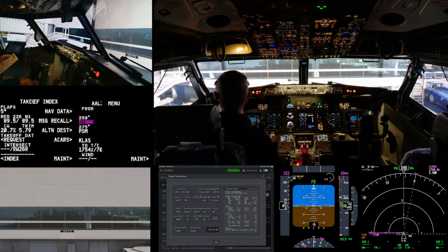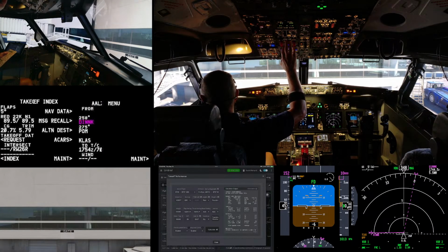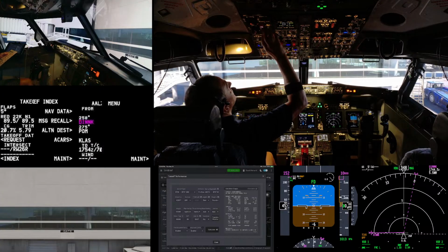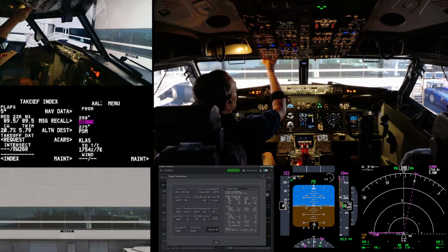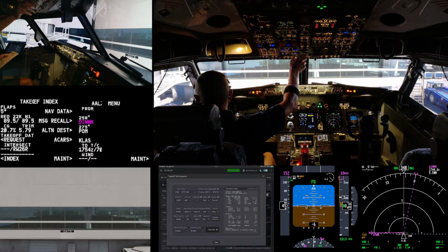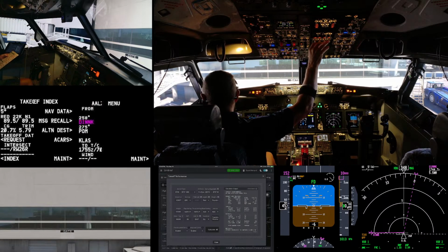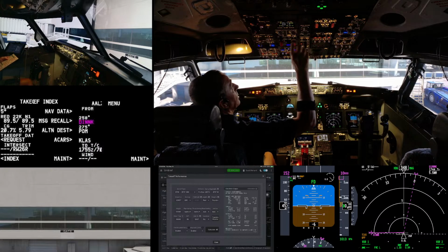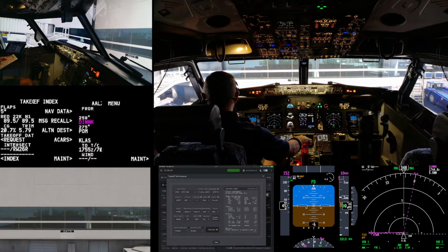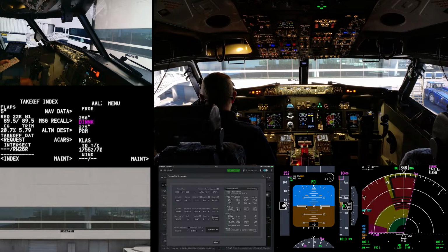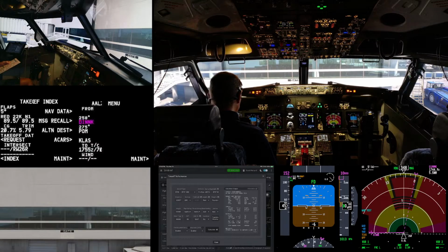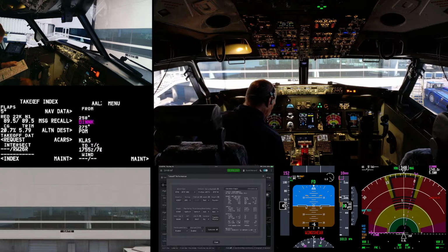Dispatch load sheets check, DC voltmeters on, batteries on, standbys on and guarded, alternate flaps are armed and guarded, off and guarded rather, fuel pumps are all off, windshield wipers are off, hydraulic pumps are all off. Landing gear, we have 3 greens and a down lever, and we'll do a weather radar check.